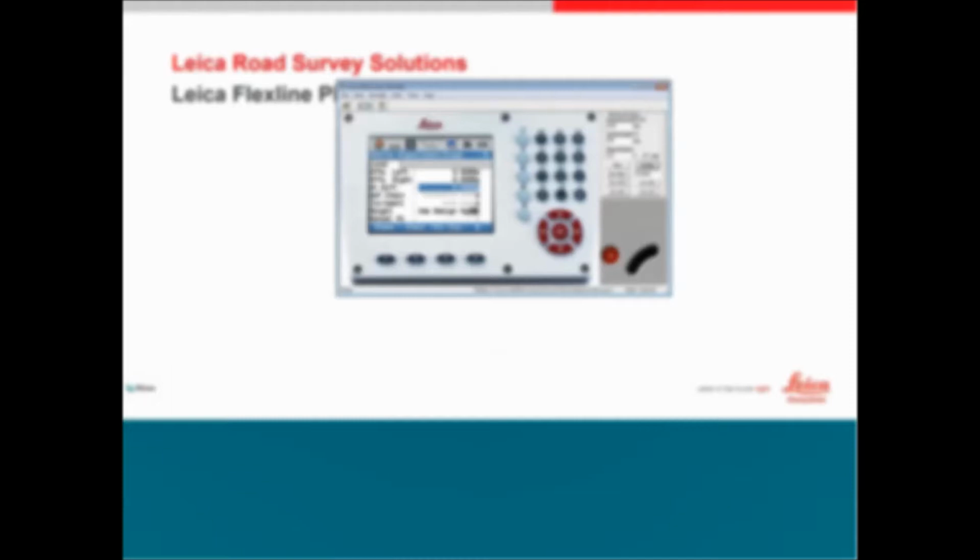You can see that there are different layers. They will be given a height difference, so you can offset it. For example, if the road vertical profile is given for the finish level, you can say that it is minus 0.5 or whatever, and then define the chainage that you want to set, for example 26760, and what increment you want to use, and do the stacking up.